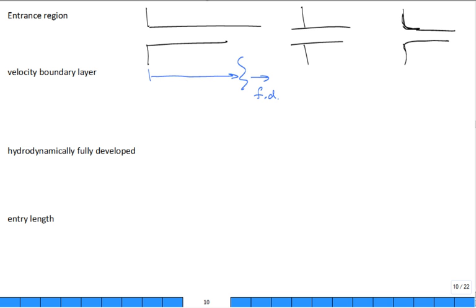But before, what's happening to the velocity profile? Let's think that it's going to eventually become laminar. And by this case, the velocity profile is that nice quadratic shape. But over here, let's say at this location, what's that velocity profile look like? Very steep, flat in the middle, and steep again. It's as if the fluid in the core hasn't felt the viscous effects from the walls of the pipe coming in. It takes some while to become fully developed. So think about the center line.